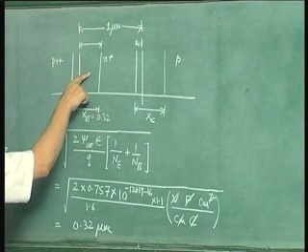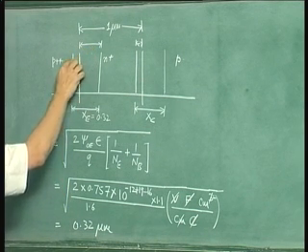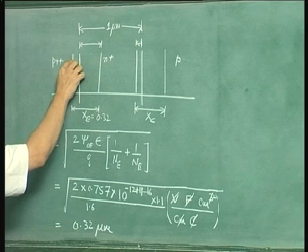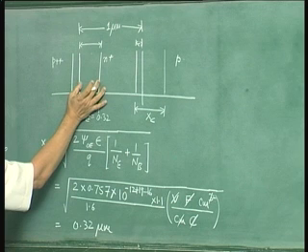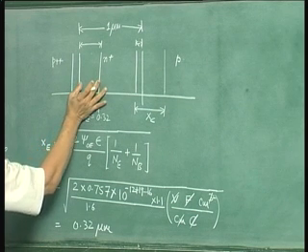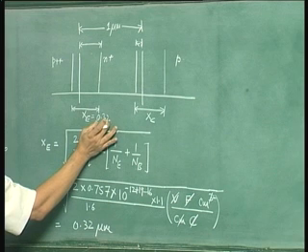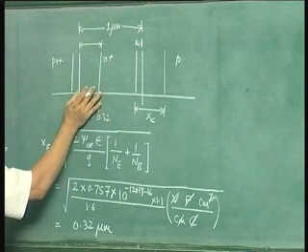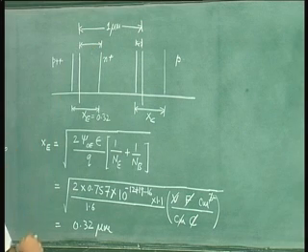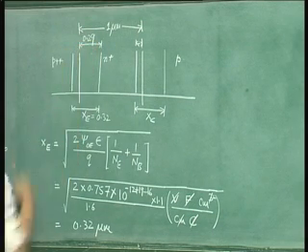Since this is 10 power 16, this is 10 power 17, this width is 1/10 of this width. So therefore, if this is 1 unit, this is 0.1 unit. Therefore, 0.32 divided by 1.1 is this particular depletion width, and that will turn out to be 0.29 microns.